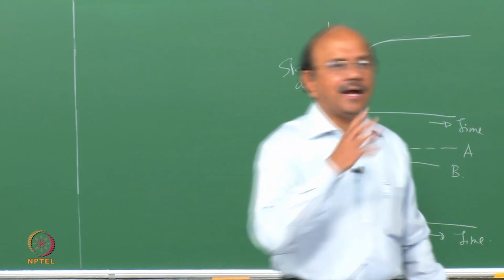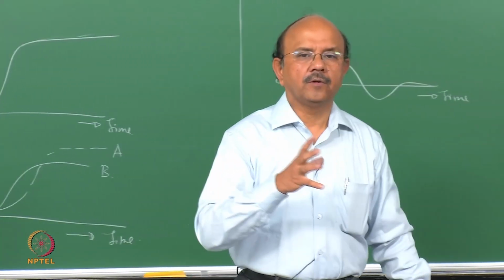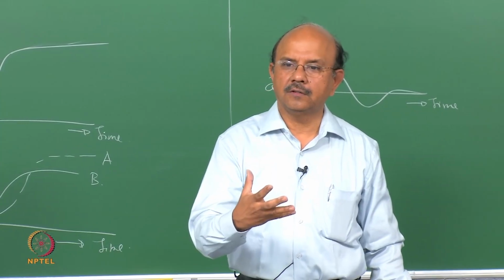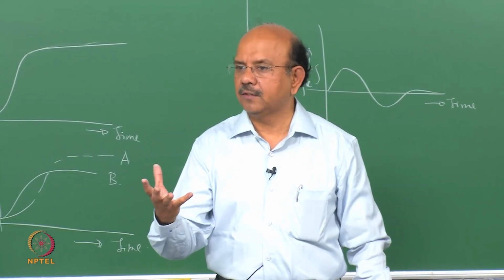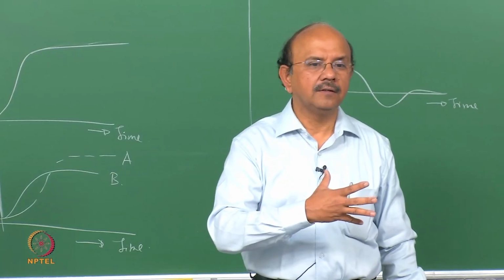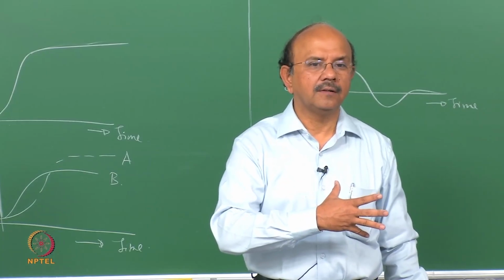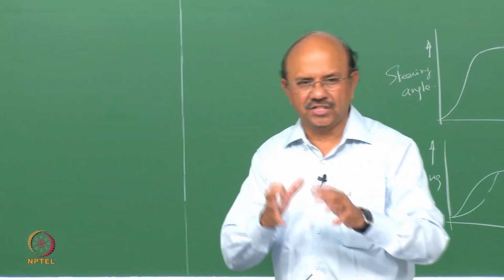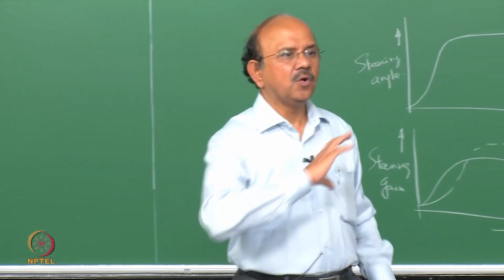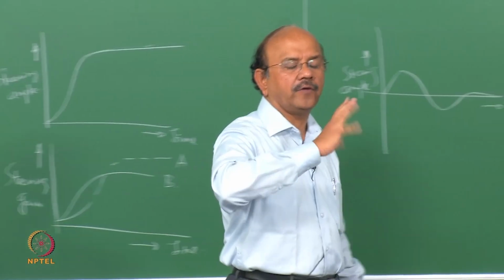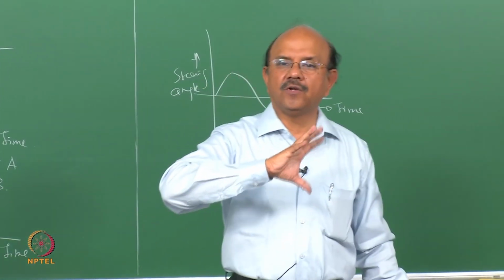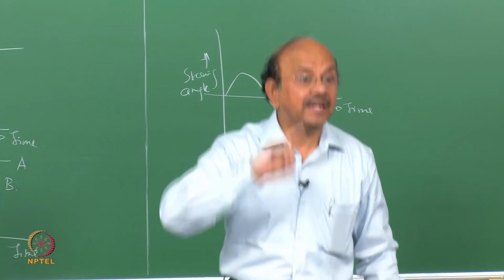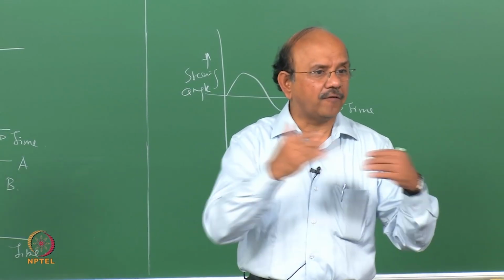Why? As we had said before, whenever there is a load transfer, there is going to be a change in the slip angles. We saw that whenever the vehicle rolls, there is a change in the slip angle. In the same fashion, whenever there is a pitch, or in other words, whenever there is a transfer of load between the front and the rear, again I am going to have a difference in alpha F and alpha R.